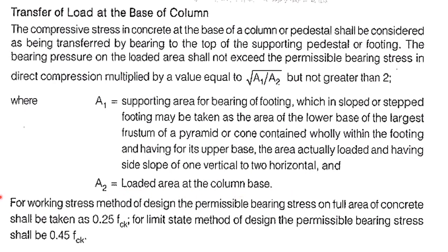And this point is the most important one. In case of footings, for working stress method of design, the permissible bearing stress on full area of concrete shall be taken as 0.25 fck. In case of limit state method, the permissible bearing stress shall be 0.45 fck. This is somewhat important for competitive examinations. 0.25 fck for working stress, 0.45 fck for limit state.